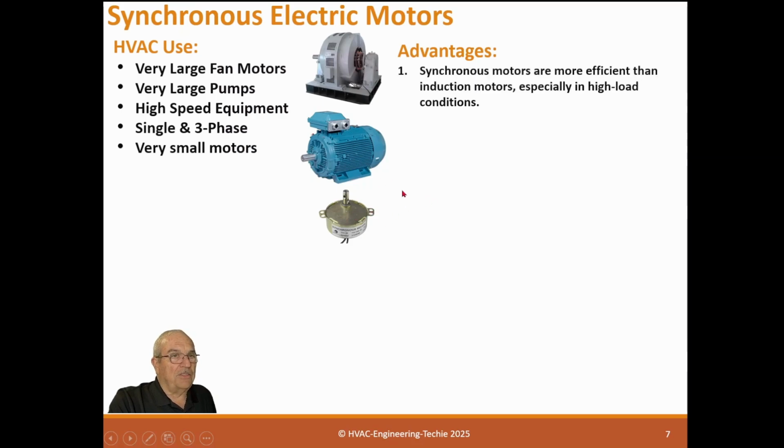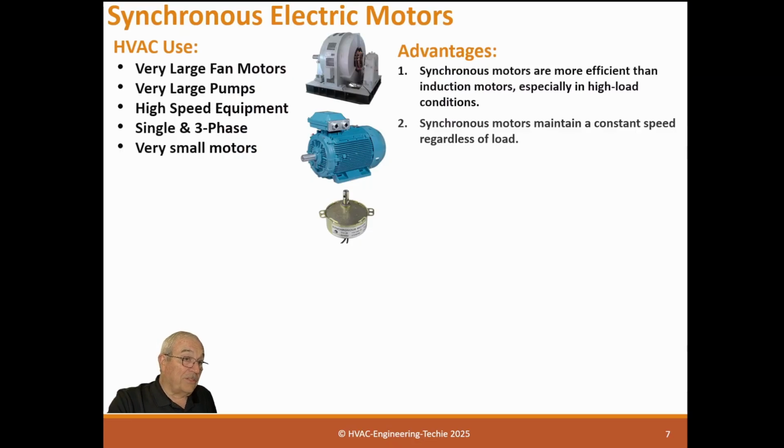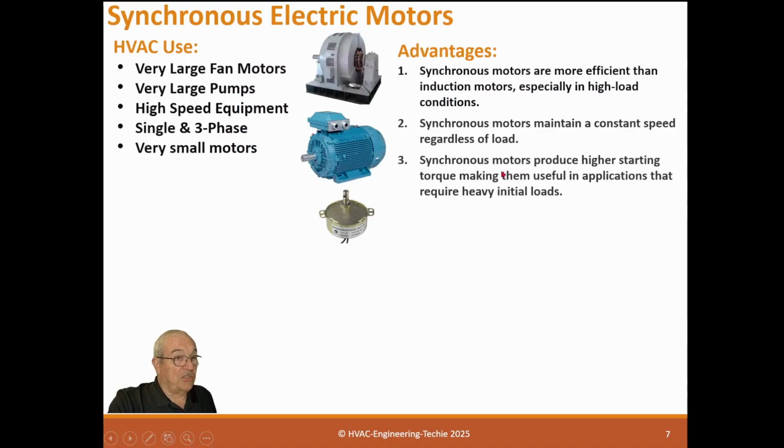Advantages: synchronous motors are more efficient than induction motors, especially in high load conditions. Synchronous motors maintain a constant speed regardless of load. An induction motor does not like to start under high torque conditions. It'll have a lot of problems, where a synchronous motor does not care. Number one, a synchronous motor has to get up to speed some way before it does. But if you have a clutch on it or something, you could speed the motor up and then put the load on it. It doesn't matter. It can accept a pretty high torque immediately, where induction cannot.